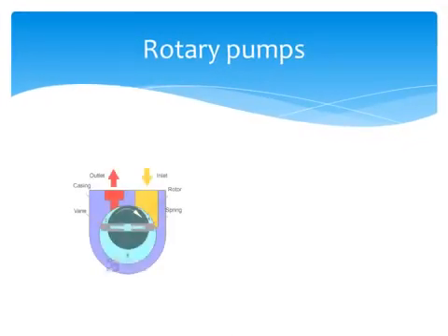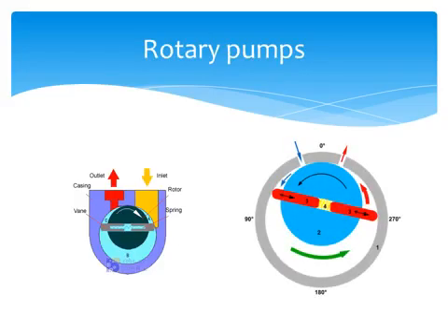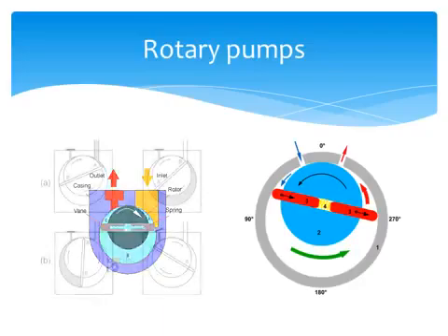Rotary pumps are defined as being vane, piston, flexible member, lobe, gear, circumferential piston, or screw pumps. In all of the rotary designs, the chamber is created progressively through rotation of the drive shaft. There may be one or more chambers open per revolution depending on the design.